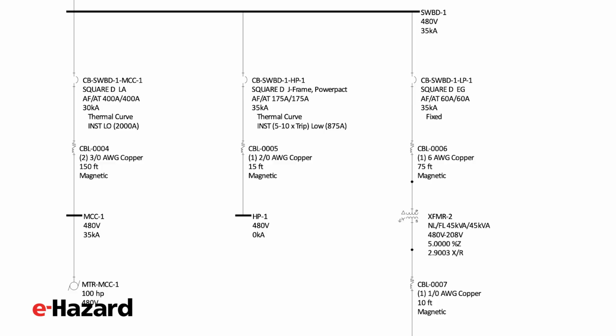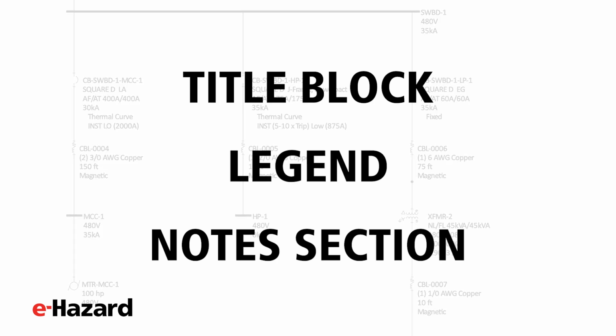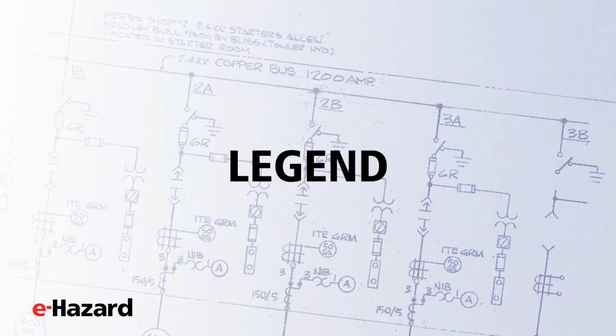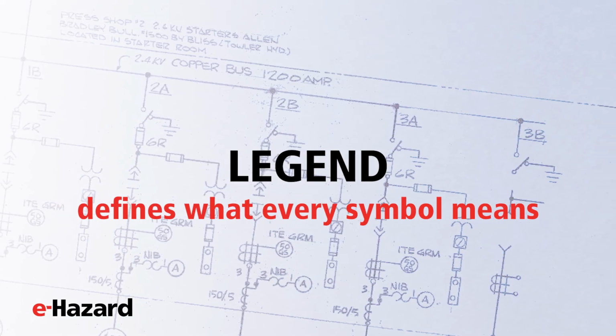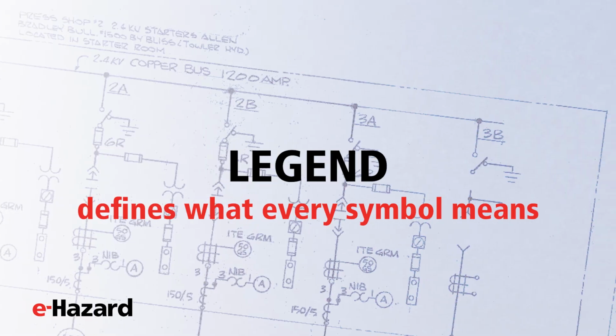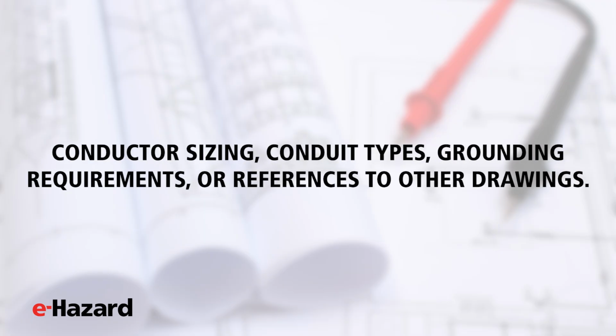Every professional one-line diagram will have a title block, a legend, and often a notes section. Don't skip these. They contain critical information. The legend defines what every symbol means on this specific diagram. While most symbols follow IEEE standards or ANSI standards, variations exist. Notes often contain specifications that don't fit neatly into the diagram. Things like conductor sizing, conduit types, grounding requirements, or references to other drawings.